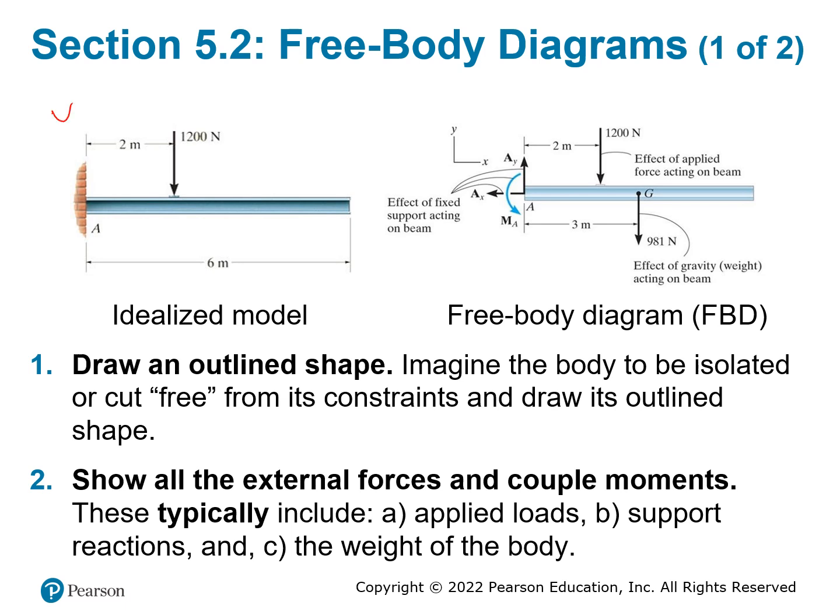In this picture right here, you see a beam from A extended to the right, and at the point A, this beam is embedded in a wall. This is what we call the fixed end, meaning this end is fixed. You cannot move up and down. You cannot rotate as well.